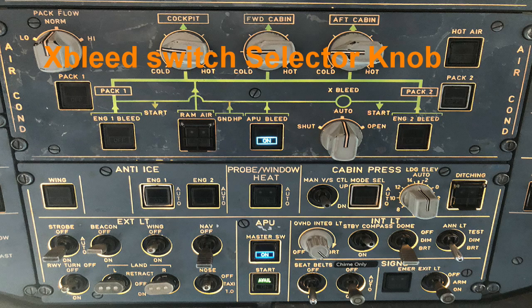So that's another condition: the cross supply of the air conditioning packs. Those are the times that you want to use the cross bleed. All right, so that gives you an idea of the switches. Again, this is strictly pneumatic control switches.